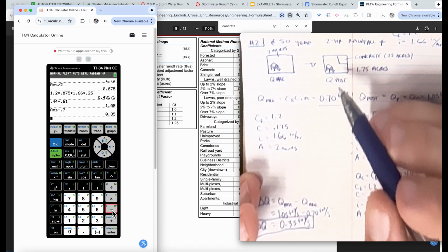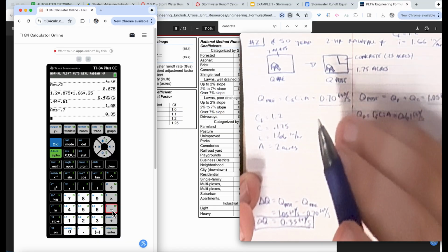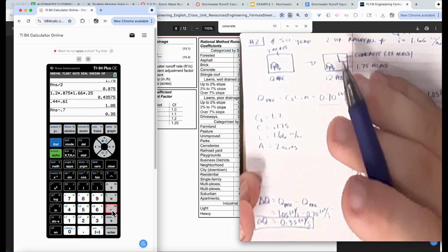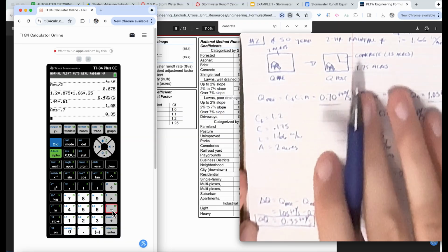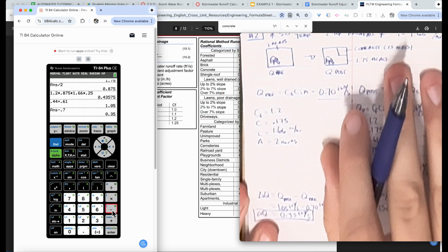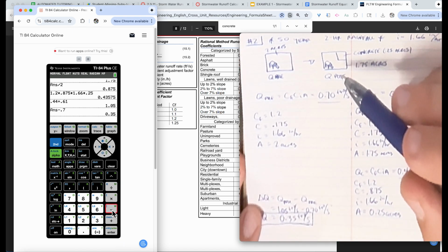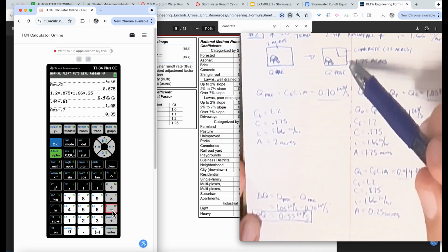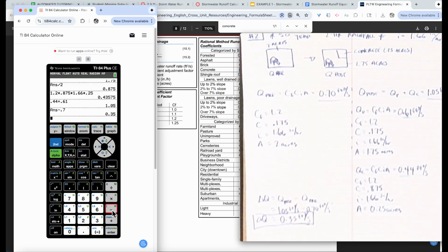Maybe we have a water collection basin so that we can store some of the rainfall and later use that, right? Maybe they have a garden in the park. Then if they store that water, they could reuse it to water the garden. All of these different options we can implement so that we can try to get delta Q down to 0. And another option, just to give you a copious amount of options, is we could also add in extra vegetation. Extra vegetation, especially for an area like a park, would be pretty great, and that'll bring this delta Q value down as well.